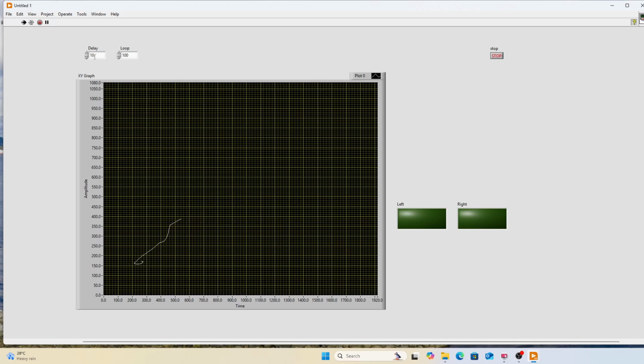And if I reduce the delay in the loop, you can actually create something more of a real-time function. But you notice that when I move the mouse up, it's actually moving down. So this is because the origin point for the graph is the bottom left and the origin point for the monitor is actually the top left, right? So this can just be inverted in software.